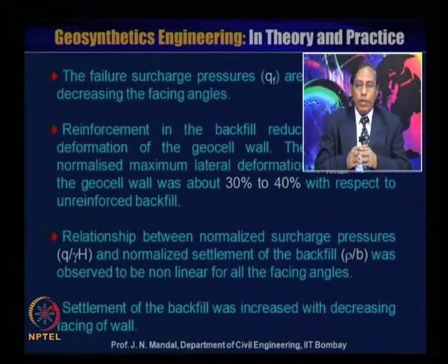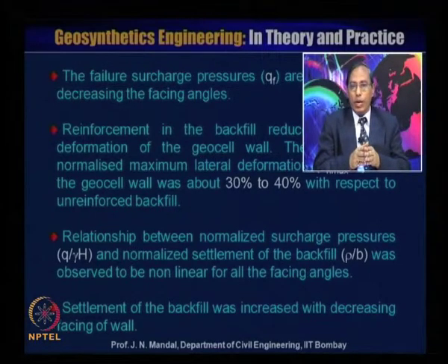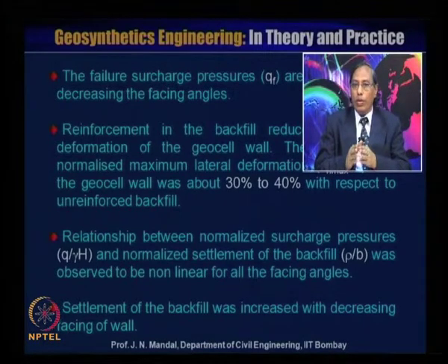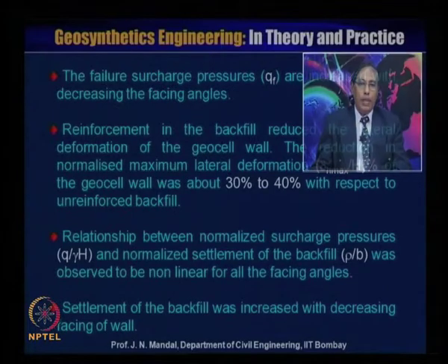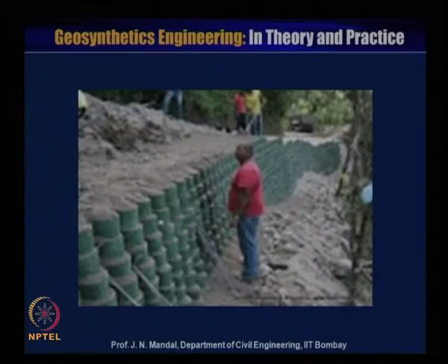The relationship between the normalized surface pressure, Q by gamma H, and normalized settlement of the backfill, rho by B, was observed to be nonlinear for all the facing angles. Settlement of the backfill increased with decreasing facing angle of the wall.